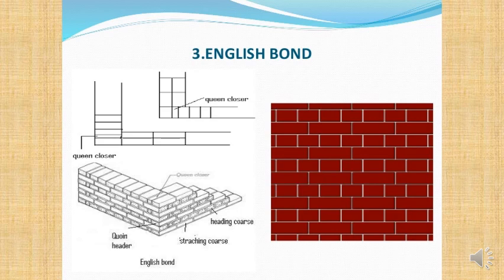And so basically you need to actually have what's called a closer, which is a broken piece of brick, one inside, and so this is called a queen closer. And so you don't leave the exposed broken brick on the edge, otherwise it's just going to fall out.